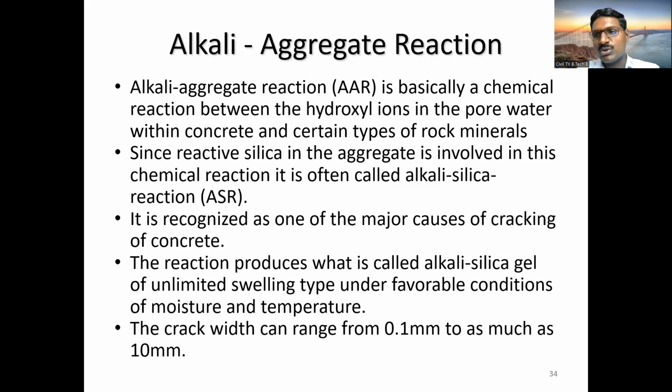Again, this alkali aggregate reaction produces the alkali silica gel of the unlimited swelling type under favorable conditions of moisture and temperature. The crack width can range from 0.1 mm to as much as 10 mm.